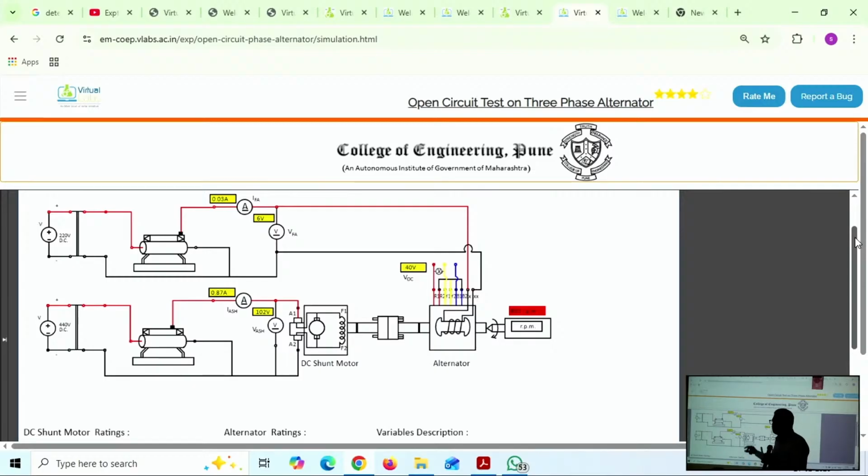So practically, what short circuit current means is very important. It means we have some value that should not be beyond the rated current. What is the rated current? I think it is 4.3 amperes. Even though the alternator output terminals are short circuited, the current flowing through these phases should not exceed 4.3, say 25% more may be allowed. You usually say 125%, if I am not wrong. Beyond that, the alternator windings cannot withstand such high current.